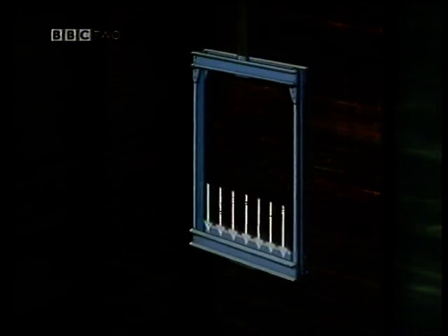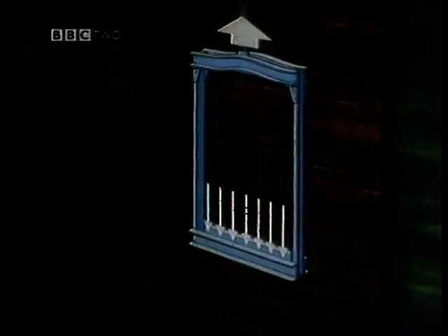The top cross-member, on the other hand, experiences effectively an upward point load at the centre due to the ropes. So this beam has to be designed for bending due to a point load upwards. And the side members, under normal operation, are under tensile loading. So this is the normal loading condition of the car frame in normal flight: 2 beams and 2 members under tensile loading. But as with the drum system, there are certain safety features, and these in turn are going to affect the forces in the car frame.